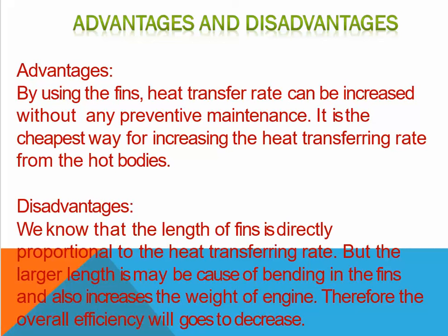And the disadvantages: we know that the length of the fin is directly proportional to the heat transfer rate, but a large length causes bending in the fin and also increases the weight of the engine. Therefore, the overall efficiency decreases.